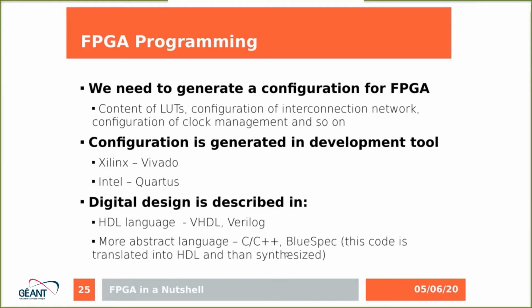This is very typical for the high-end FPGAs, but if you buy a low-end FPGA, then you can use the free version of this tool. So in your case, I think you have the NetFPGA. In your case, you will need a license to synthesize the bitstream for this FPGA. It depends on the type.